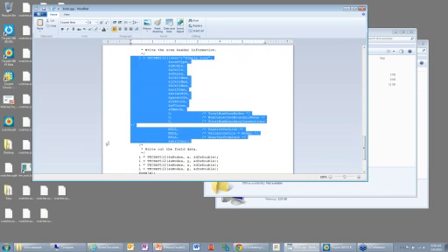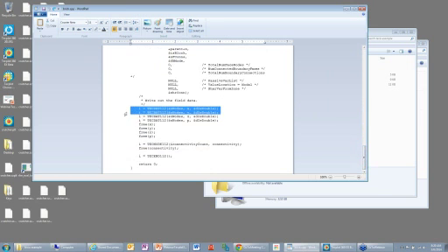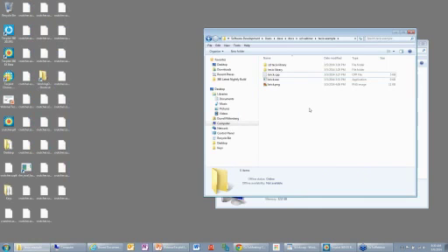Then for each zone we call TecZNE112 to pass it all the metadata about the zone size and the solution time, and whether it's sharing variables or connectivity. Then finally, we have to call TecDat to output the variable data and TecNode to output the connectivity. And then finally, TecEnd to tell the TecIO library that we're done writing data. So you only have 5 function calls. Yeah, 5 APIs will be called here.